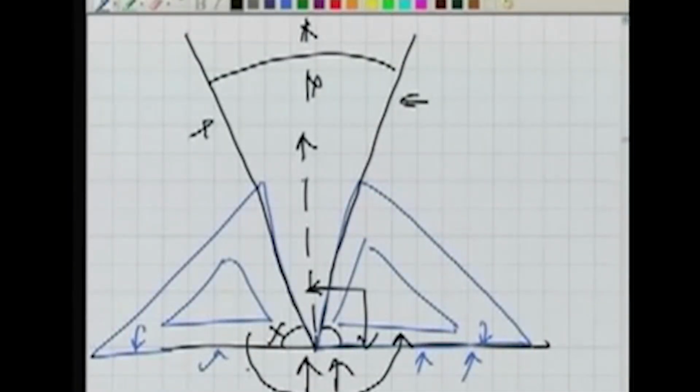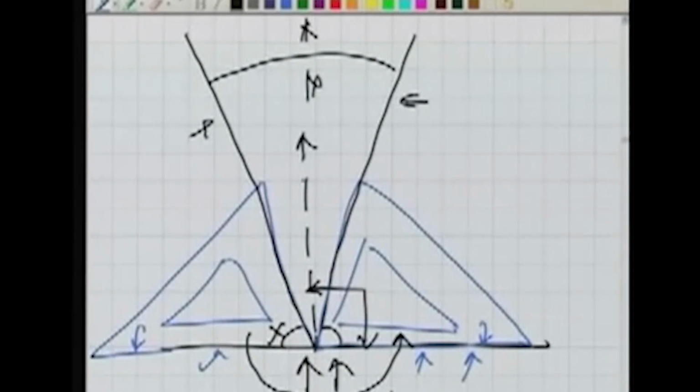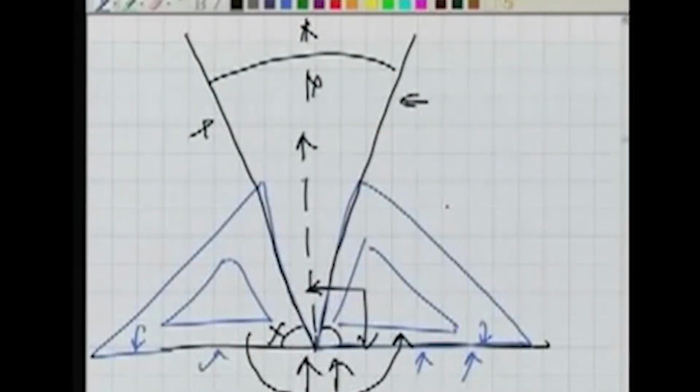We can still do our job with the set square which is wrong in construction, because this line is at 90 degree angles. Now what we will do in all our adjustments henceforth, or while we are taking the observations with theodolite or many surveying instruments, we make use of this principle. We change the face, we reverse our way of taking the observations, and many of the errors are eliminated. So we should keep this principle of reversal in mind.